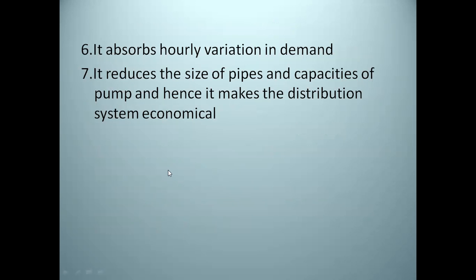Then the next function is it absorbs hourly variation in demand. If there is a variation in demand, that is, in the early morning there is a large use of water, at evening there is a large use of water, and at daytime there is very little use of water, then this variation is absorbed by the service reservoir.